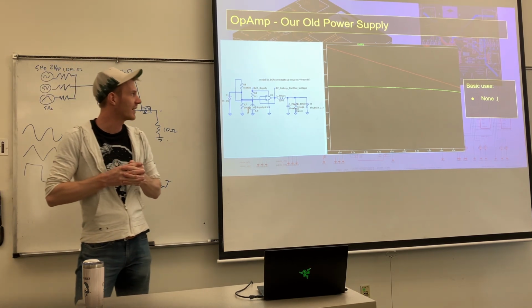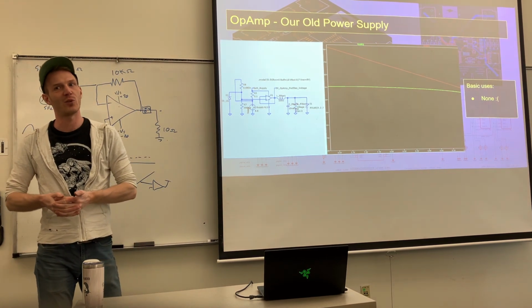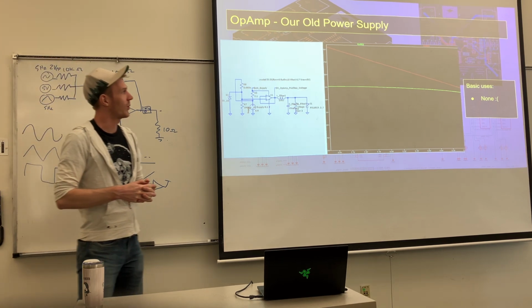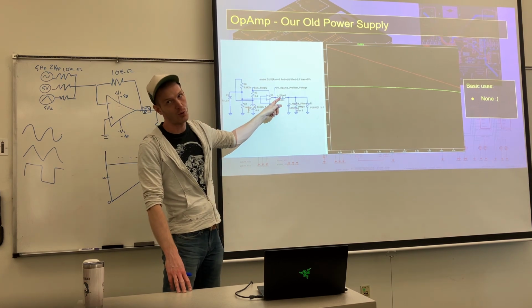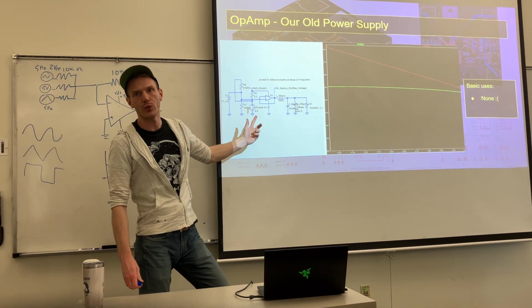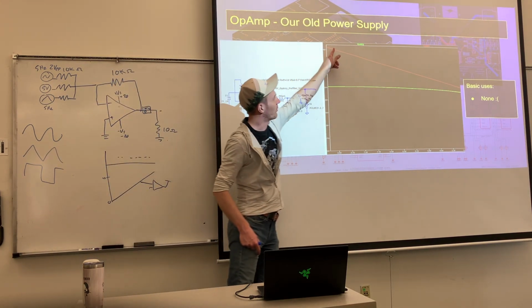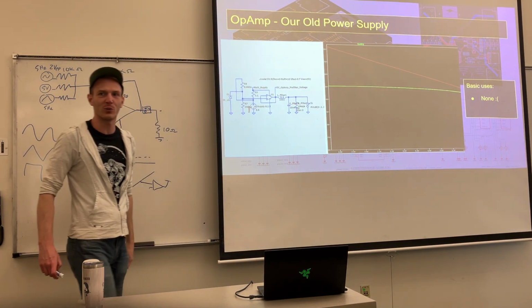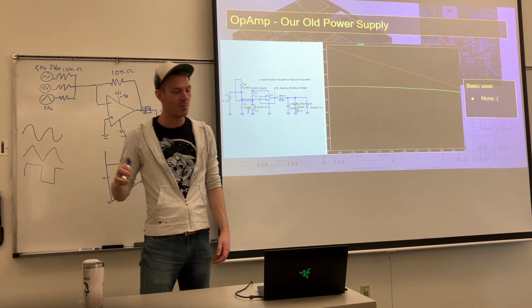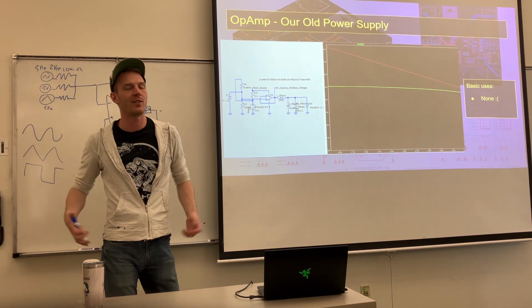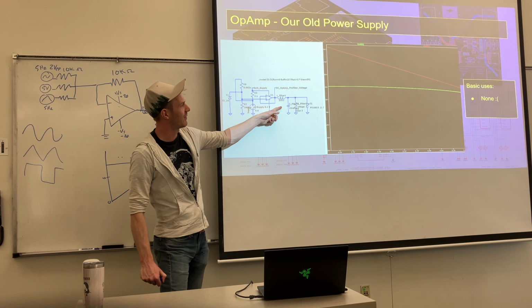Perfect, that is exactly it. This is what is called a voltage follower, because it follows the input voltage on the non-inverting terminal. So we're developing 5 volts here, we're applying it here and saying this will always be 5 volts. The battery is not always 5 volts. We haven't talked too much about batteries, but battery voltages start really high when they're fully charged and they drop off. If you have a high precision system which needs a more stable voltage than that, that's not what you want. So we are saying, great, we are now just outputting 5 volts.